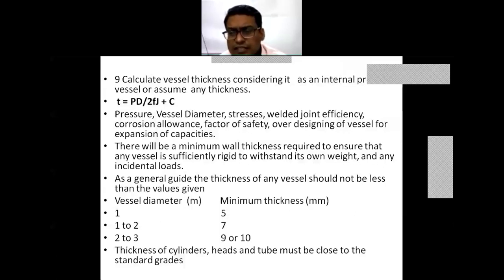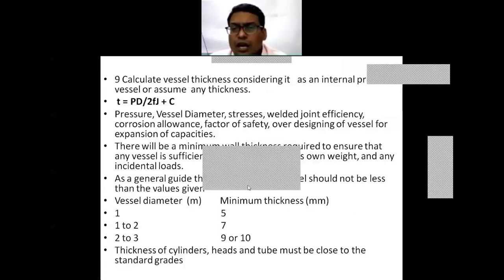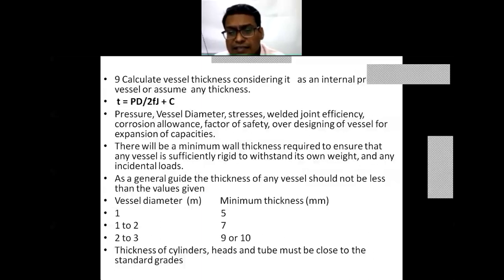So the thickness of cylinder heads and the tubes must be close to the standard grades. Whatever the theoretically calculated thickness is, irrespective of that, we go for the higher thicknesses, because accordingly I have to select that particular thickness which is available in the market.